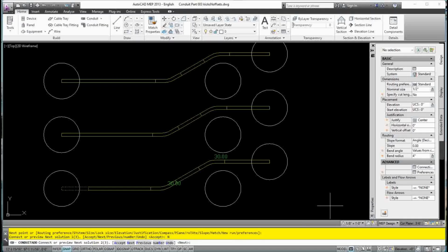What about, do you think we can get 15? Oh, look at that, 15. So, instead of erasing and drawing to see if something would work, with AutoCAD MEP, you do it once, and if it will fit, it will display it. So look at that. I can do 15s, 45s, and 30s. How much time did we just save there? Okay, so let's say we are happy with this 30-degree angle.